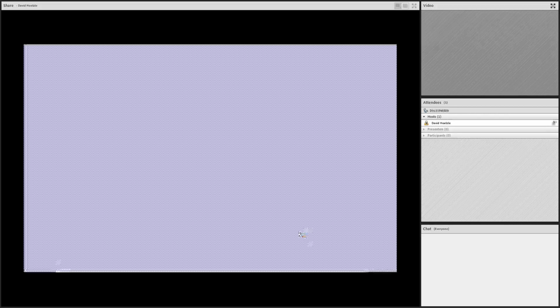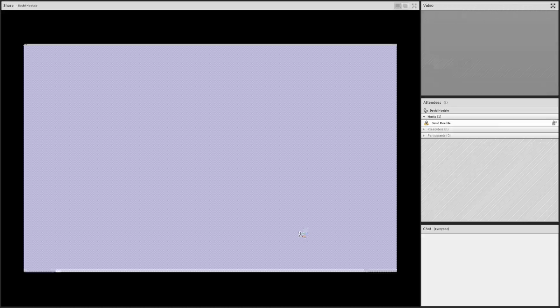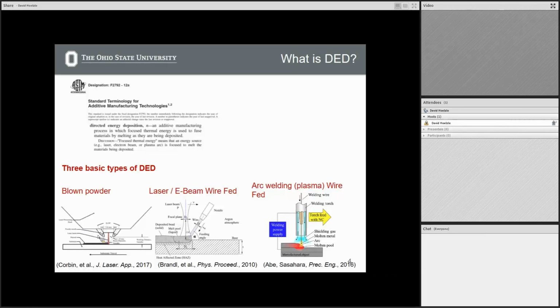These are schematics from that survey paper. I think the schematics are very good at overview, but they don't really show all that well what's going on. Sorry, this is probably too small to read. But this is showing some of the components a little bit better. These are powder jets. Here, this is just showing a cross section. A lot of these systems will have 4 or even more of these powder jets. Some of them will have a complete sheet where it's all coming from a ring. But then you have a laser in the very center, so these are all along the same spot.